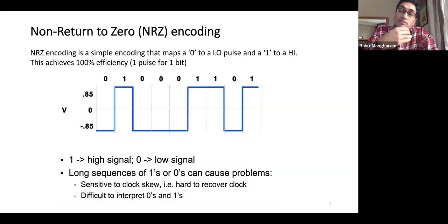So suppose you're sending me this data, right? The first time you send me this 0, I say, okay, that's a 0. And I'm just basically counting 0, 0, 0, 0, 0, 0, 0 till this point. And then you basically send me a 1. And when we have this transition, I say, great, now I'm getting a different kind of energy from the signal. And therefore I treat that as a way to provide me some feedback that this is a clock boundary. This is a bit boundary over there. So in some sense, we are kind of tying in the signal itself and the timing of the signal with the signal.